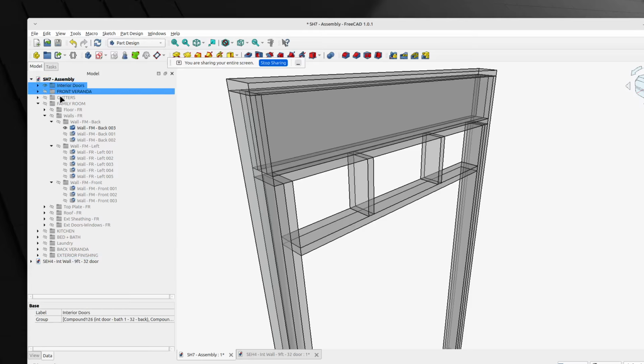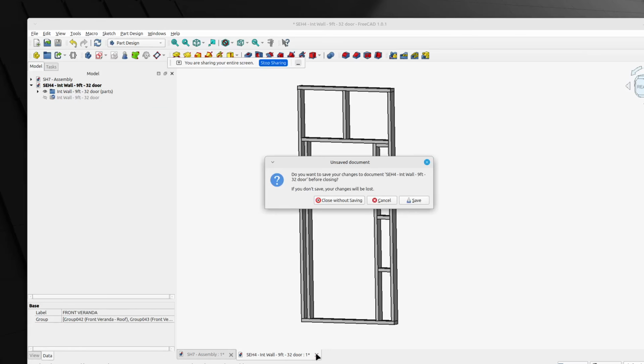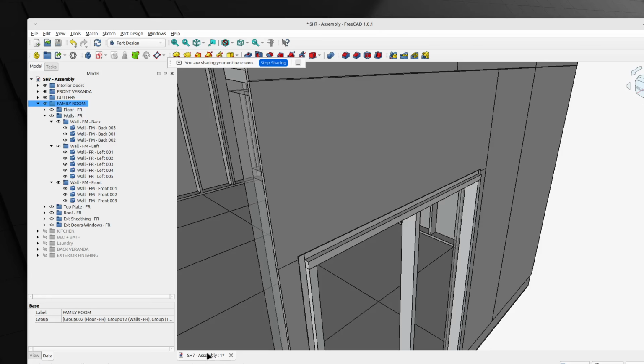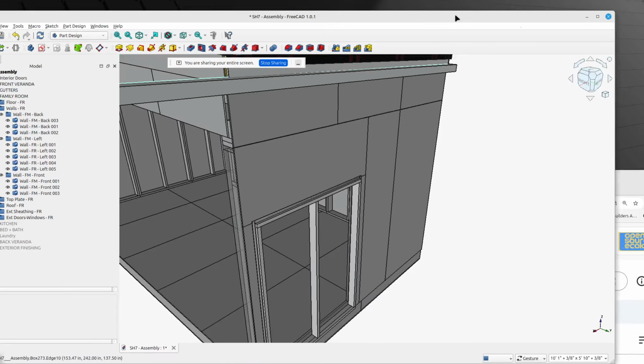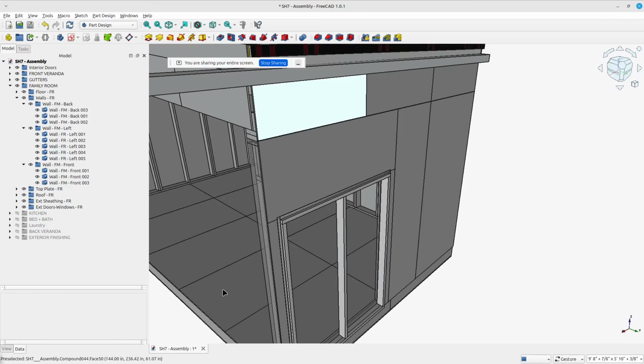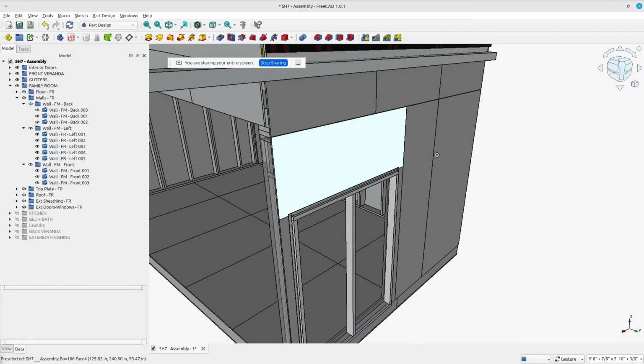Let's say we open up all the parts. I'm going to hide the other one. In assembly, this is a huge file, and you might get cluttered up in what you're looking at. So you can simply cut and paste and create new files with subsections of the house, so that you have everything organized really well. Because this is really an accounting question. Like I mentioned, in this master file there are 800 parts, and the individual files have a dozen each. So there are literally multiple thousands of parts in this entire document.